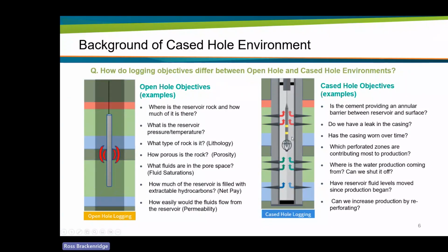Okay, a bit about cased hole. What do we mean by cased hole logging? Well, it's slightly different to open hole logging. Open hole logging is when we've just drilled the well. We use wireline tools to go into the well and take readings directly from the formation. The only thing between the tool and the formation at that point is borehole fluid.